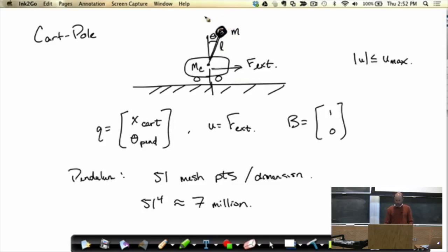So maybe if we can say that, in this regime, the system looks simpler, and I could use some very simple basis functions up here. Like if I'm close to the top, maybe I can say the system looks almost linear, right? And in the case of linear systems with quadratic costs, that was close to the case we did last time, we are going to have not only an efficient algorithm, but an almost closed form, a closed form numerical expression for the dynamic programming solution at the top.